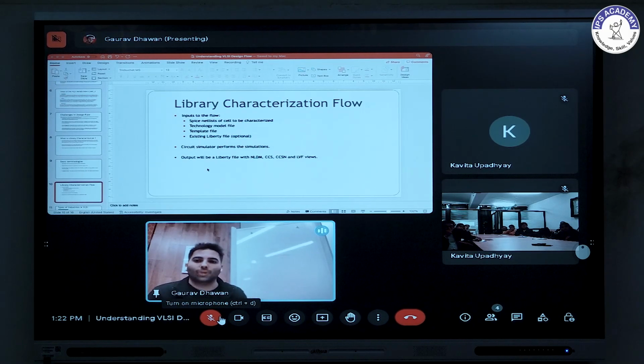Any change in input, if there is a block and we are giving the input signal, with that change in the input signal, if there is no change at the output, it means that power was consumed somewhere within the circuit, but it did not cause any transition at the output. But the power was consumed due to internal switching activity. Whatever power was getting consumed there, that is called hidden power because that is hidden somewhere. It's not causing any effect at the output. So that hidden power we model. So that hidden power gets modeled under the input pin in the library.